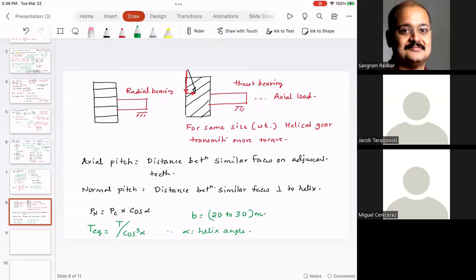I will give you the helical gear nomenclature, addendum, dedendum, addendum circle, dedendum circle, various ratios. Then I will give you the design recipe. There is not much theory to discuss in helical gear, because the idea is take the helical gear, convert that into spur gear and use the equations and tables for the spur gear, and get done with it. So next class, I will give you the step-by-step recipe for helical gear and I'll work out the problem.